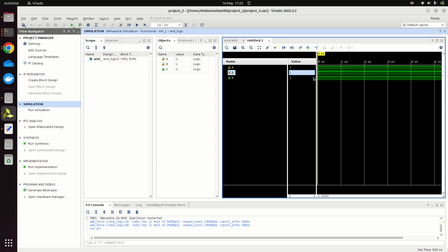Okay, so if you just minimize it, hopefully you will be able to see the logic of AND that you can verify. So if you see here, A and B, these are the inputs. That's 1 0 1 0 with a 50% duty cycle, and then 25% duty cycle with 1 and 0, then 1 and then 0 and 1. So what we are performing here is an AND gate, and 1 1 gives output 1. So this simulation is verifying that we are having the correct things.